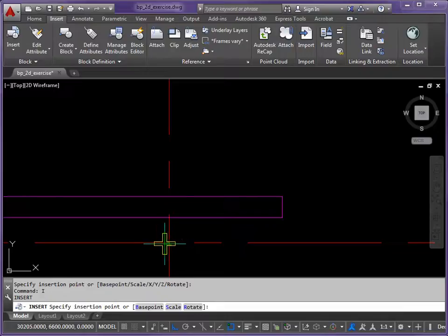Find the intersection. It's not showing me the intersection there automatically. That's a concern. I definitely want it to go to the intersection. So this is where I can use the tab key on the keyboard, and this will look at what's happening in this area. So if I tap the tab key with maybe a half a second in between, can you see the way it's scrolling through the various object snaps? Perpendicular. When I get to intersection, that's when I use my left mouse button.